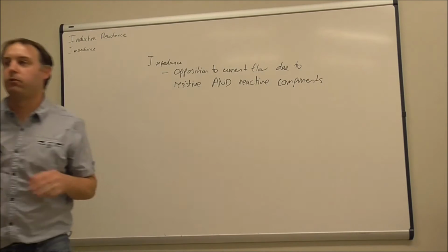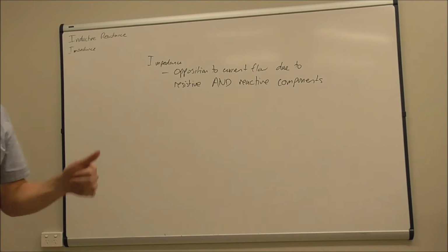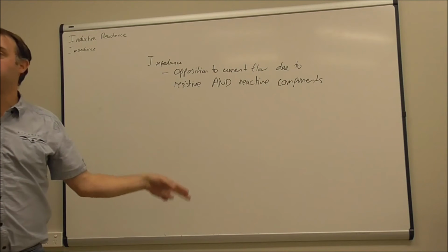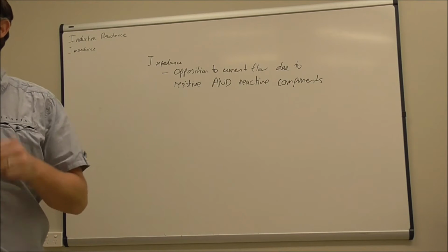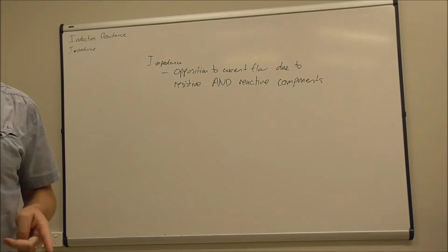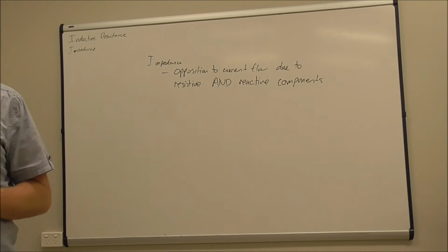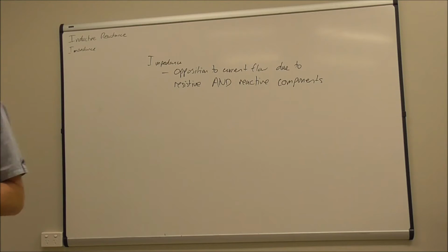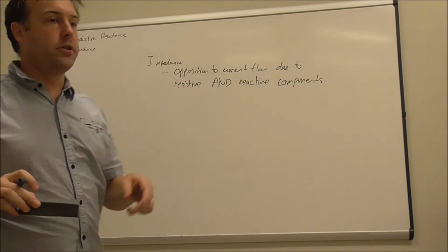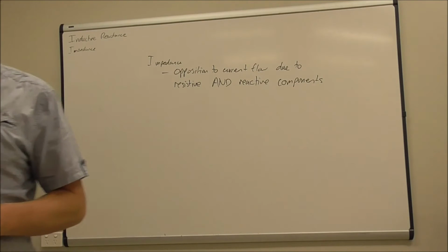So when I talked about reactance before, I was talking about pure reactance, so only the component that is due to the frequency. So an ideal capacitor would be a purely reactive component. An ideal inductor would be a purely reactive component. In practice, we very rarely get those. So if you have a look at the big inductors you've got, you'll see it has DC resistance. It's about 4 ohms.